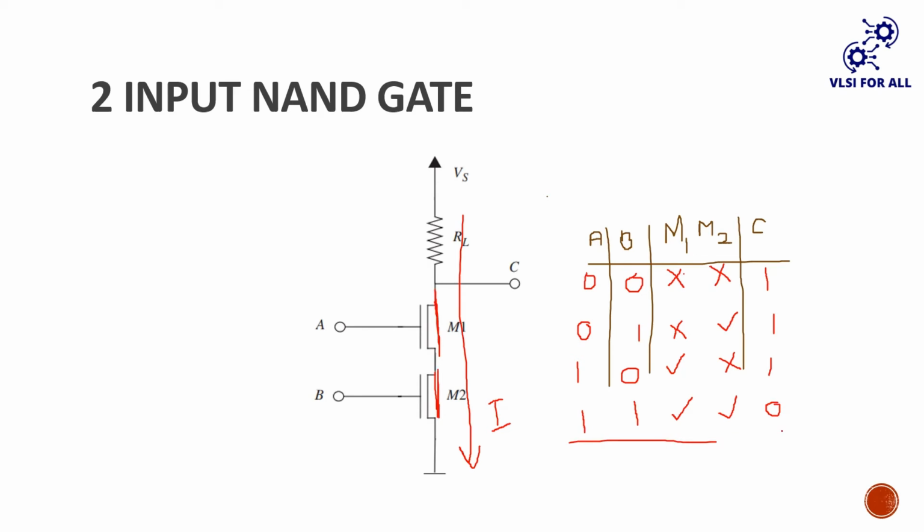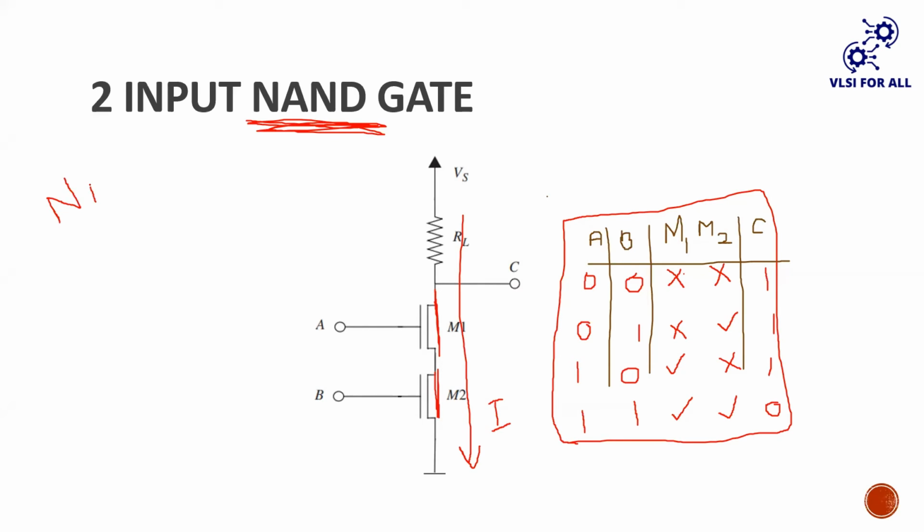Now you see guys, here in front of you, there is one truth table for the combinations of input 0 0, 0 1, 1 0, 1 1. The output is 1 1 1 0, which follows NAND gate only. So guys, remember, in NMOS technology, because we are considering N channel MOSFETs now. In NMOS technology, if at all the MOSFETs are connected in series,